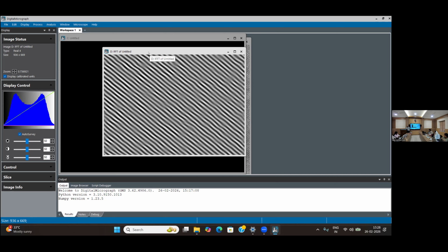Then go for TEM, because in TEM we are analyzing a very small region, and we can find different morphology, different types. It's like you are searching something in a stadium. You are looking for a motor pin, like a small pin in a stadium. The sample inside TEM, it's enlarging anything like a stadium, because the maximum magnification is about 1.5 lakh times. So we should have a very good idea about our sample, then only we can easily get some good images,